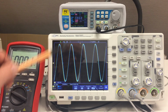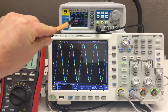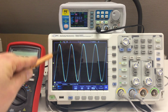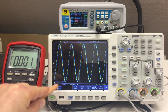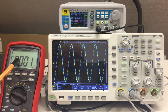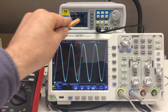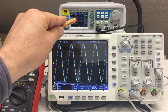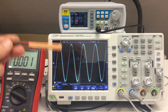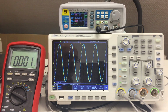Let's see. So I turned down, you probably can read it, you have to believe me, the start frequency here to 1 Hertz, and we are still at almost 300 Hertz at 0 volt input voltage to the VCO. So turning down the start frequency on the unit itself doesn't work. We will need a negative VCO voltage to get down to the 20 Hertz I want.